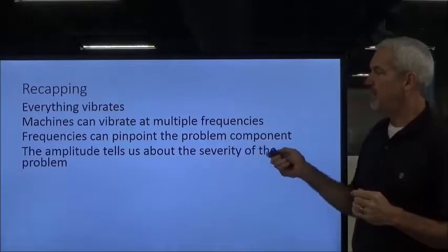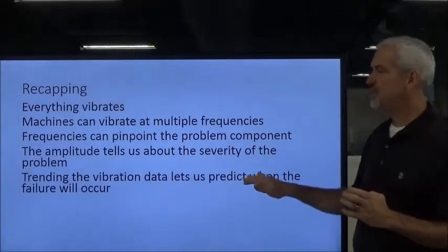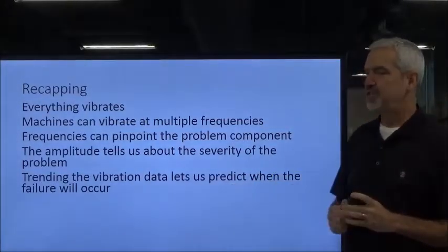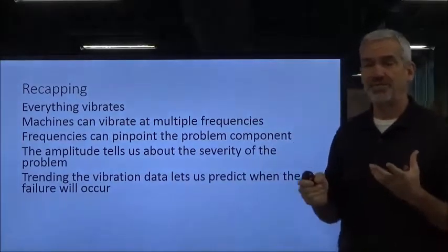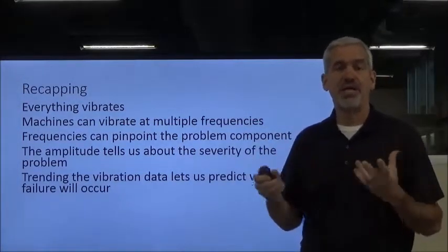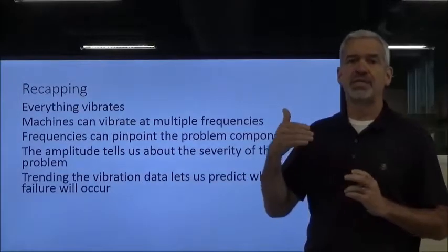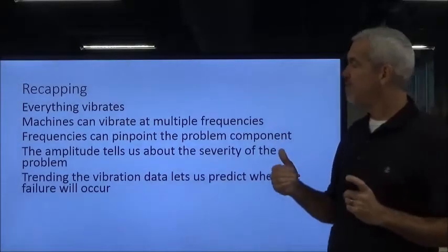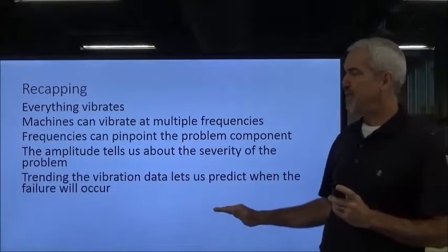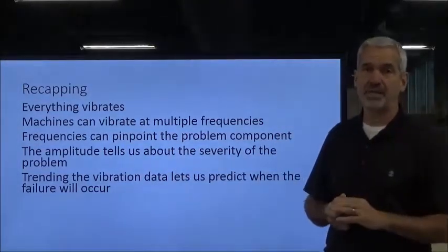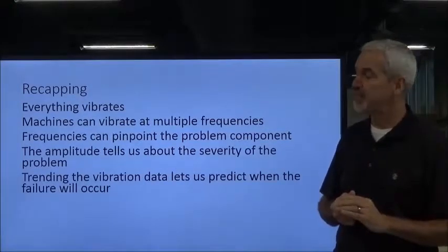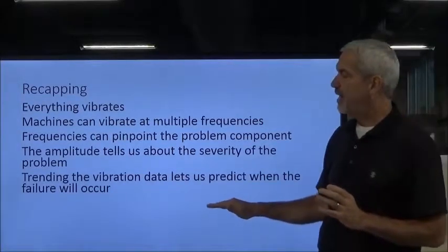All right. Also, trending. This is really important. Trending this vibration data. Okay, you get your baseline data. You remember me talking to you about that one fan bearing that I had go bad over the weekend when it wasn't even running. Well, I was getting my baseline data. And from that point, I'm going to watch that bearing over a period of maybe even a couple of years. We saw the life expectancy of bearings and things. So I'm going to trend that, and I can watch it.